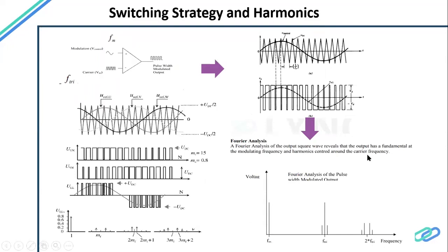And then we have to see what kind of harmonics we expect. Okay, so PWM is generated through a carrier and a sine wave. What we are more keen on is what kind of frequency this has, because those frequencies will have harmonics around them. We can see the harmonics are at multiples of this carrier frequency.